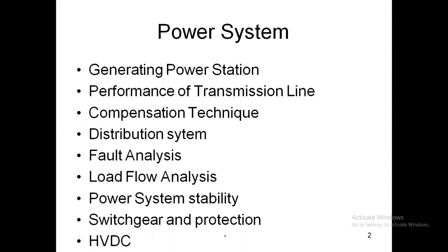There are different kinds of electrical power plants, like the steam power plant. In a steam power plant, you burn coal and generate steam from it, and you run the turbine with that steam. Your generator is coupled with that turbine, the steam feeds mechanical power to the generator, and the generator converts the mechanical power into electrical power.